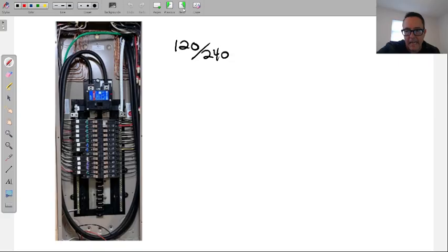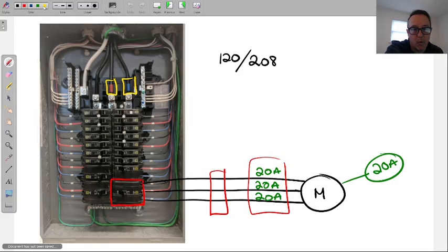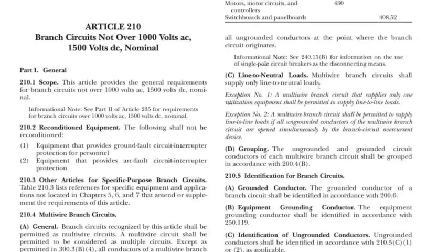All right. Now this one, no worries about turning it all off at the same time. It has one handle, like the 2-pole. This is a 3-pole and has one handle. So these shut off all at the same time. Big worry again is that neutral carrying some kind of load where a breaker wasn't shut off simultaneously at the same time. And it goes into explaining that on the neutral side here.